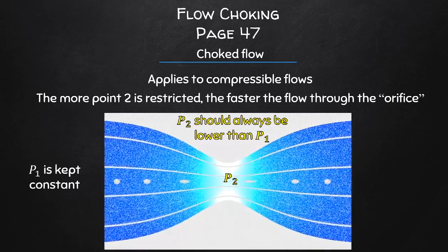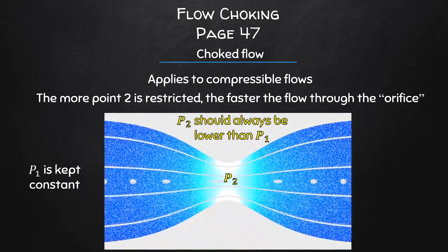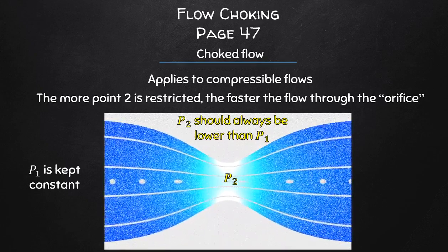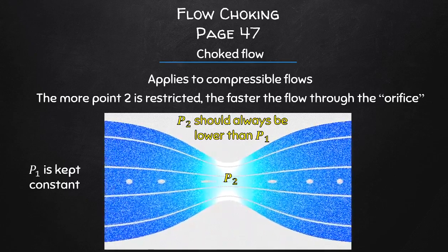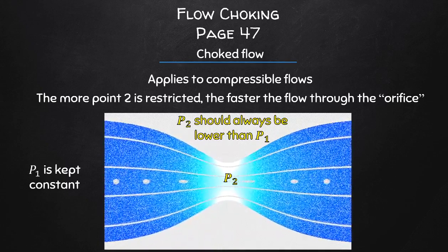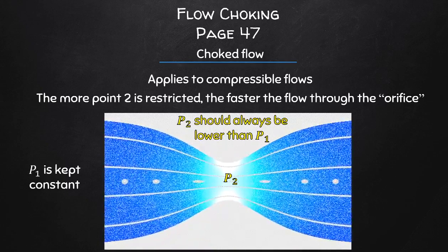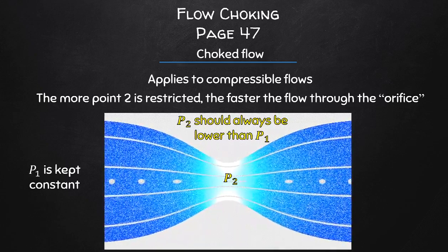There is in fact much less restriction in the throat than behind the throat because of the way that the particles interact with the throat as they enter it and pass through it, such that the velocities will then speed up considerably. The density drops also as a result, and this gives rise to a drop in the pressure being measured here.